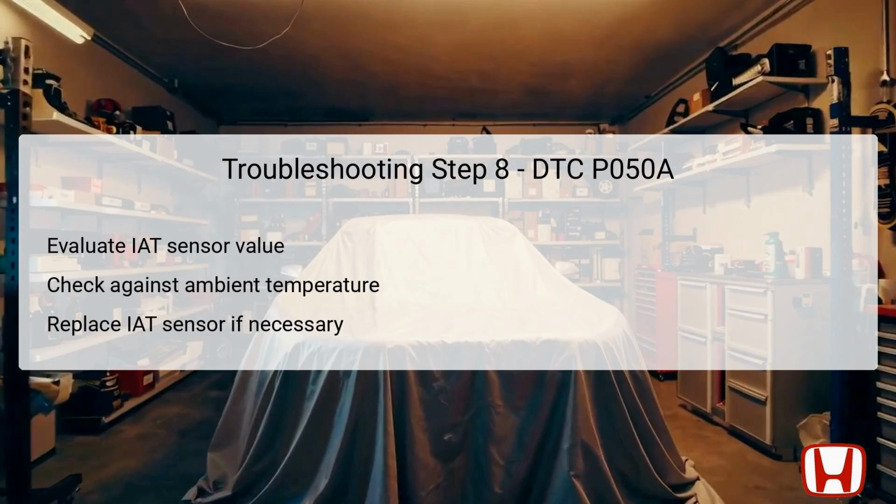However, this step should also include inspection for any dirt, carbon buildup, or damage in the throttle body. Cleaning or replacing the throttle body might be necessary based upon this assessment. Monitoring IAT readings is crucial for maintaining effective engine operation during various conditions.